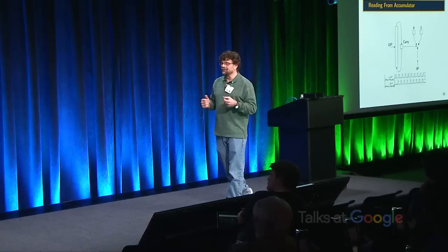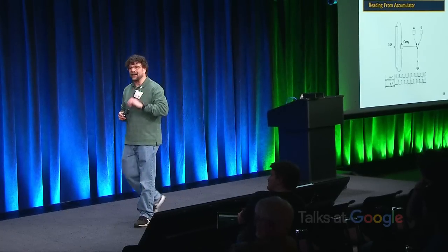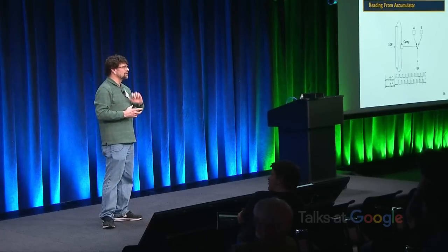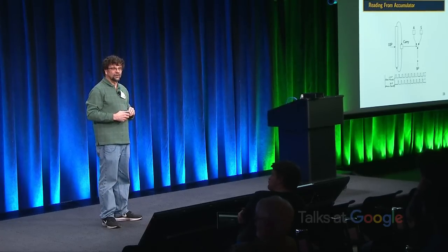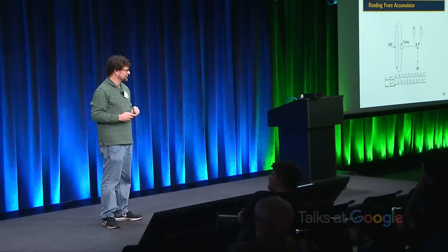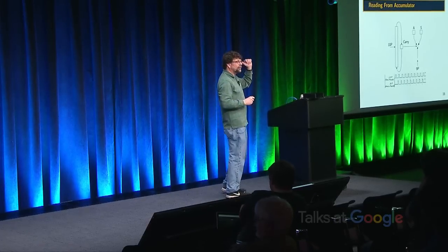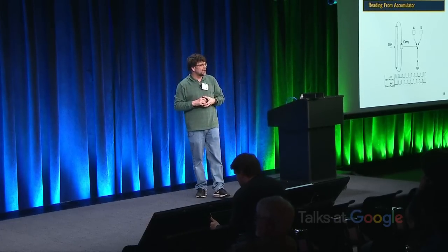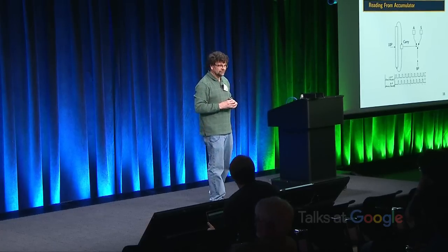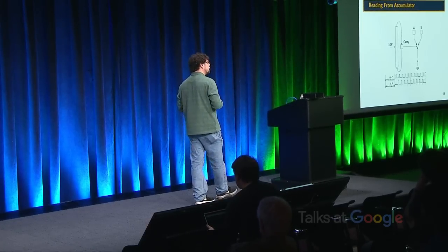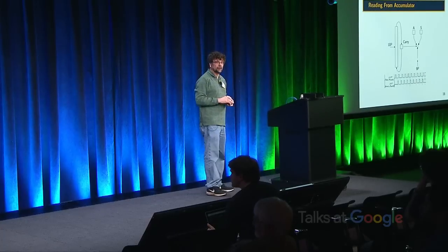And it turns out that if you think about it for a second, the carry is exactly when I need to switch from outputting on one of the terminals to switching to the other. So we start out sending out the S port. As soon as the carry hits, we switch and send the rest of the 9 pulses out the A port. And this is how we read information from the accumulators.